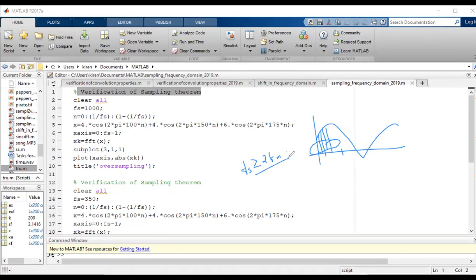That's the sampling theorem. And the equality here, 2FM, is called the Nyquist rate, which forms the boundary. So for example, let us take this particular wave here. I have taken this particular wave which contains three frequencies. One is 100, and there is 150, and there is 175. Of course, a signal can have several frequencies. 175 here is the maximum signal frequency.